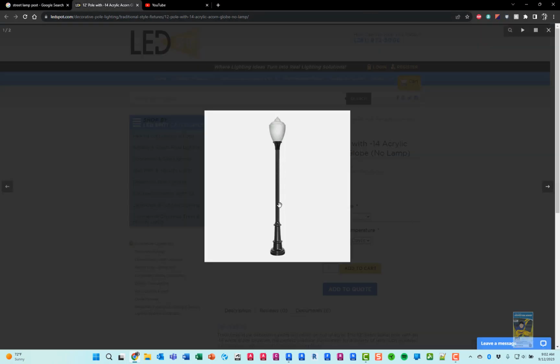And that's okay. So what we need to do is we need to start with a light fixture family in Revit. We need to understand the light source and its position relative to the level, and then placement of the height, if so we want to make it adjustable, and then deal with the housing and then deal with the structure. So that's the goal.